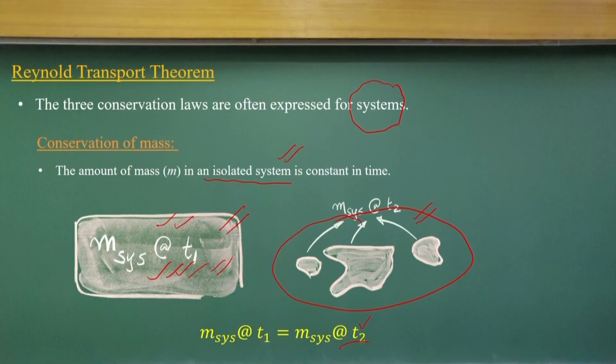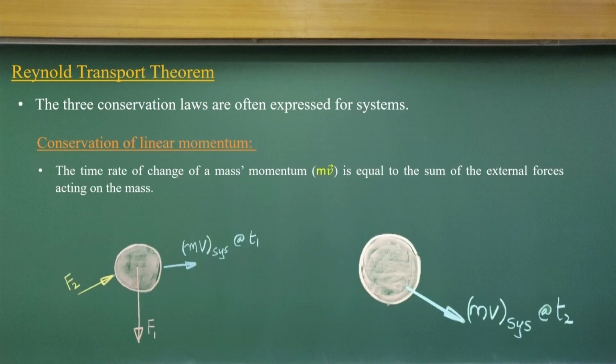That is the very basic concept we use for solving fluid flow problems when we consider fluid systems. Now, as you might have solved a lot of physics problems on solid body translations, rotations and so on, you apply the basic concept of the linear momentum equation, which you know: force is equal to mass into acceleration, or mass into dV by dt, or the rate of change of momentum flux.